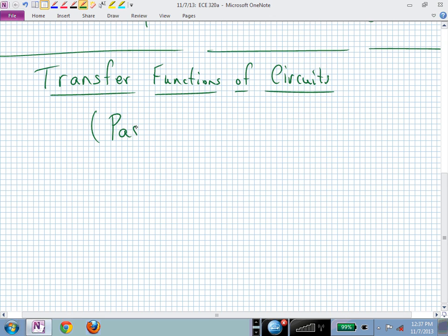And these circuits, we'll be playing with a couple of different types. We'll look at passive circuits. Passive just means that we do not have any active devices in our electronics or in the circuit. So really that means Rs, Ls, and Cs. Those are passive devices. We don't have to power those or energize those to get them to work. Active in this case means now we have op amps. Can we build circuits out of op amps, or by the appropriate selection of elements around op amps?